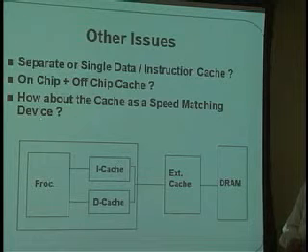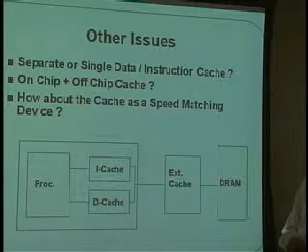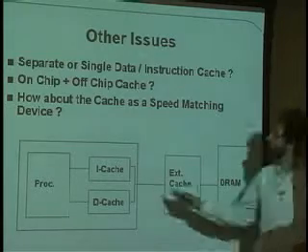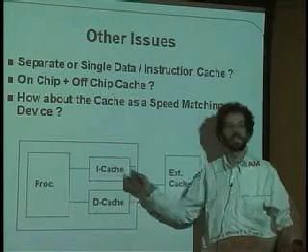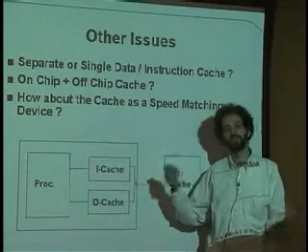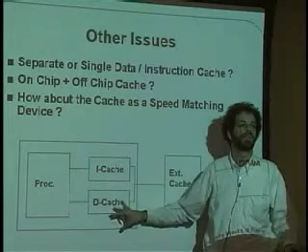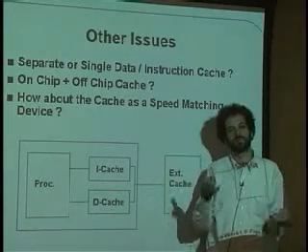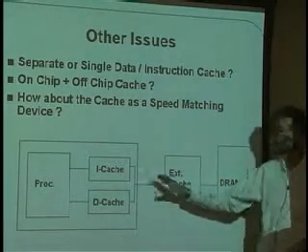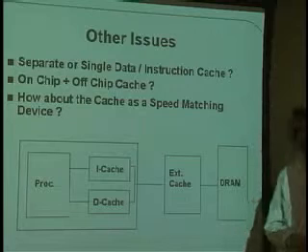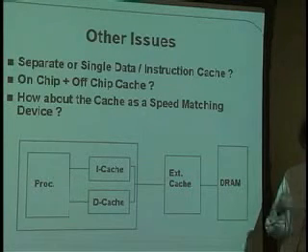Unless for some reason some programs are more data intensive than others. So sometimes you find that this cache is being used more than this cache, or this cache is being used more than that cache. And if that's ever true to a great extent, then usually it would have been better to just have one of them where regardless of which is being used more, the total is available to both. But the reason you want them separate is what? So that you minimize the collisions between the two sides, right?